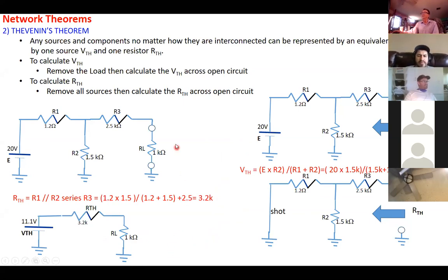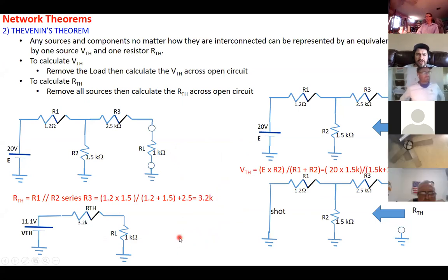Okay, so any question for Thevenin? Is there any advantage of using any of these theorems against Ohm's law? Is there any specific use for each and every one of these, or can we choose? Well, they still use Ohm's law everywhere. However, what they try to do is, you get a circuitry with too many resistances or different sources, and finally they want only a very simple circuitry, only one voltage and one resistor. That's what Thevenin is for.